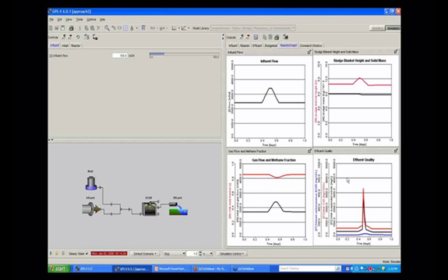So the black line here shows the suspended solid concentration. As soon as the flow increases, there is a slight increase in the effluent solid concentrations. But as the solid blanket height crosses a certain level, there is a significant loss of solid. When we reduce the flow rate, the solid loss from the reactor goes down and comes back to the level which it was before.